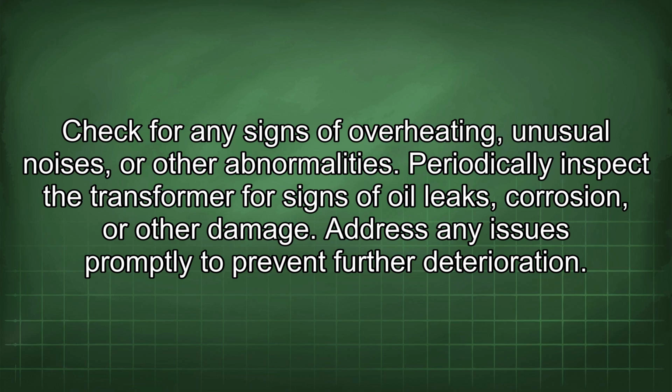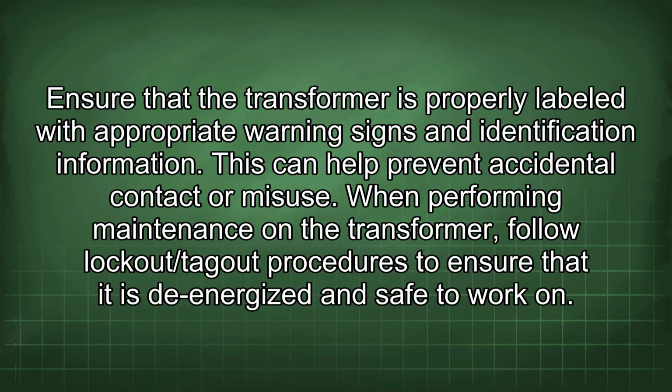Periodically inspect the transformer for signs of oil leaks, corrosion, or other damage. Address any issues promptly to prevent further deterioration. Ensure that the transformer is properly labeled with appropriate warning signs and identification information. This can help prevent accidental contact or misuse.